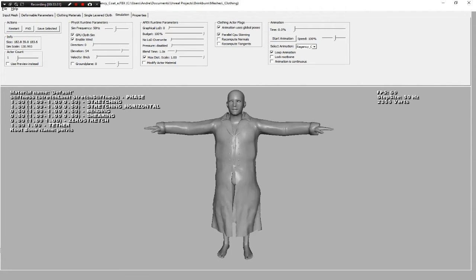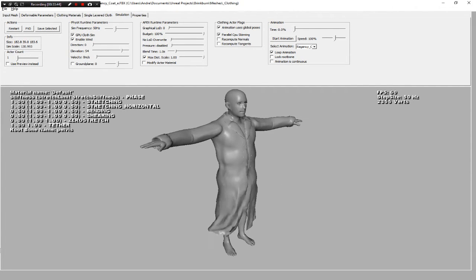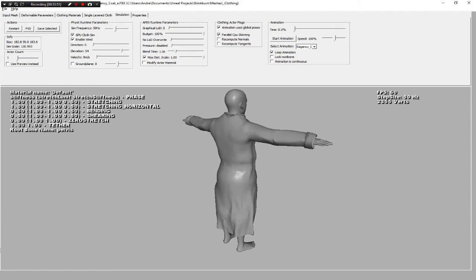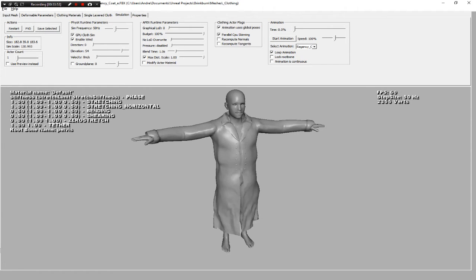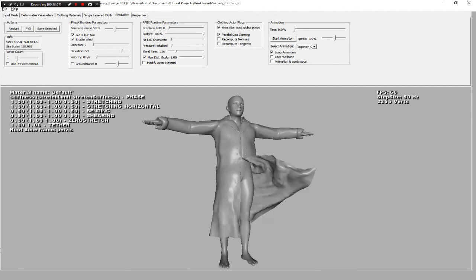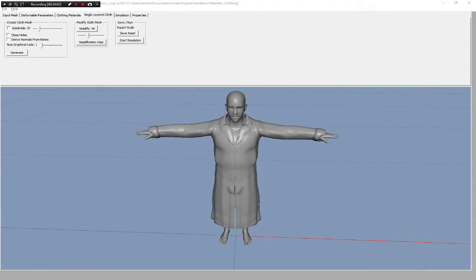You can even make almost the entire coat with physicality. Just bear in mind, you can't paint everything because this has to hang on to something. In this case, all these vertices are hanging on to the rest of the coat. And if you paint up to here, you still have to leave parts unpainted. Otherwise, the coat's just not going to work. It has to have something to hold on to. But anyway, this is how it's done over here.